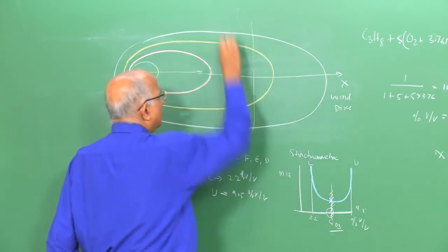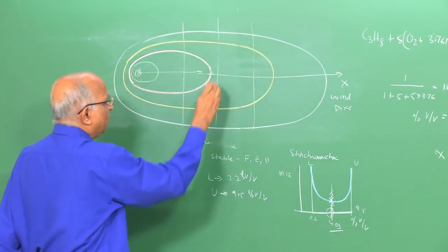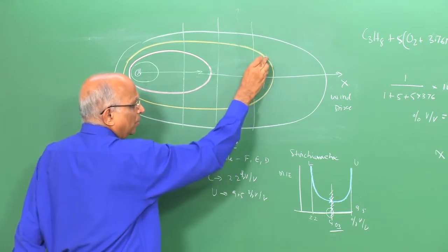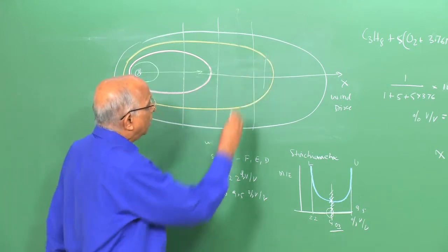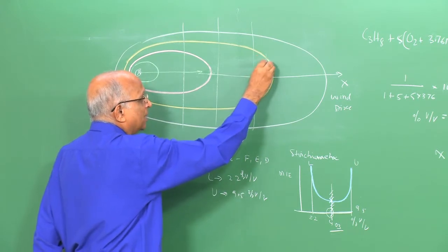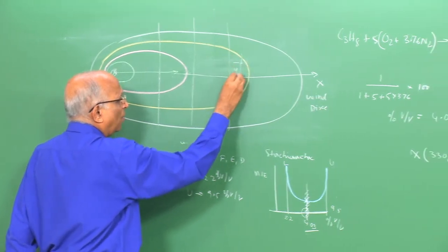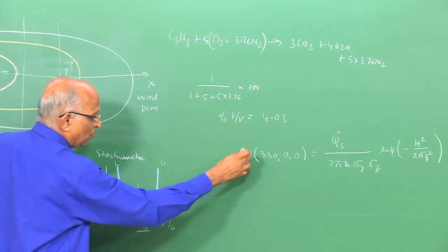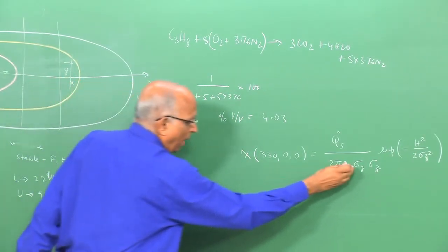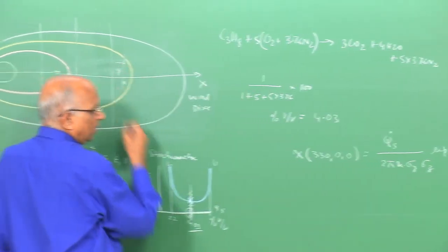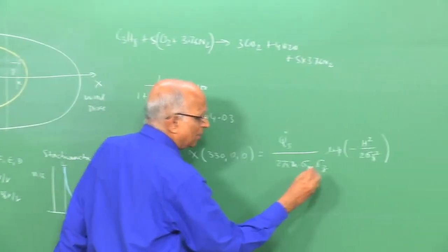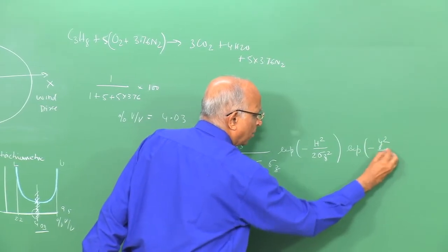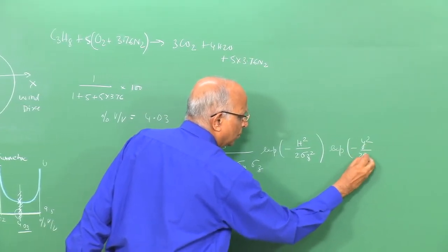Well, these are the lateral directions. You have the maximum concentration over here, and along the lateral one I can determine the concentration at this particular point. All I say is that at this particular station x, I get this value of sigma y and sigma z. At this point, I now introduce the value of exponential minus y squared by 2 sigma y squared.